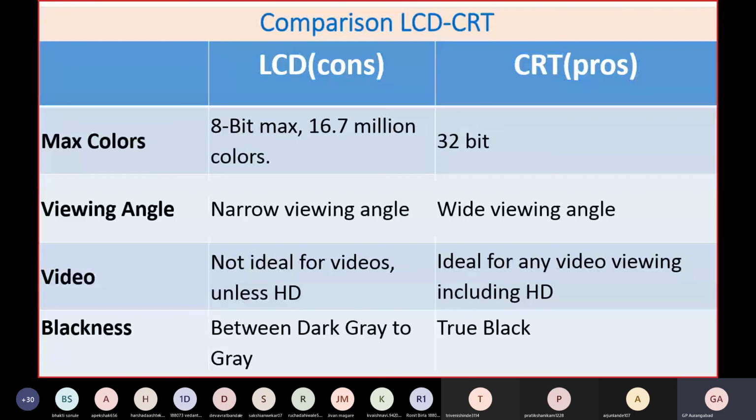Then you have to decide how much is to be passed and how much is to be blocked, which is decided by the original intensity. By applying a potential, the LCD will be twisted, untwisted or proportionately twisted, and accordingly you will get a bright light or a darker light.